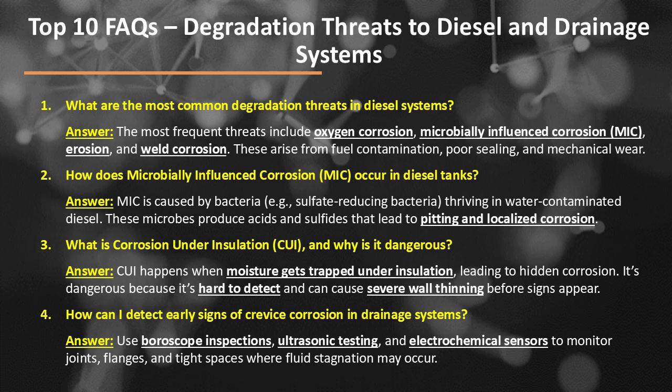Question number 2. How does microbially influenced corrosion or MIC occur in diesel tanks? The answer is, MIC is caused by bacteria such as sulfate-reducing bacteria thriving in water-contaminated diesel. These microbes produce acids and sulfides that lead to pitting and localized corrosion.